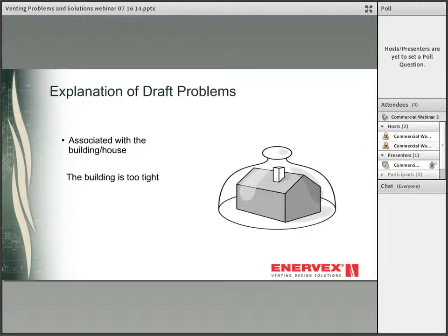Possible solutions are to install a properly sized outside air intake ducted to the bottom of the fireplace. This must be relatively large and should in most cases exceed a 6-inch ID. Actual size depends on the fireplace opening. It could be powered by a fan or blower, and you want to provide supply air to the room in which the fireplace is located. You can install a mechanical venting system, but make sure that the air can be drawn into the room in which the fireplace is located, and also make sure it does not adversely affect the operation of other heating appliances like the home's furnace.